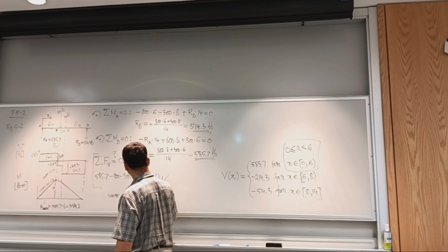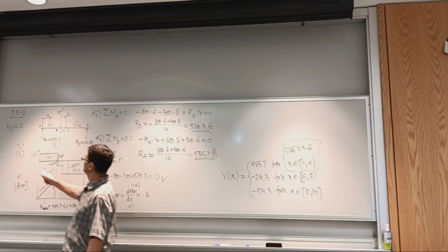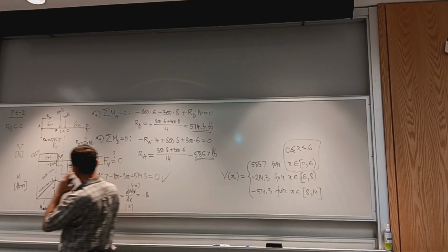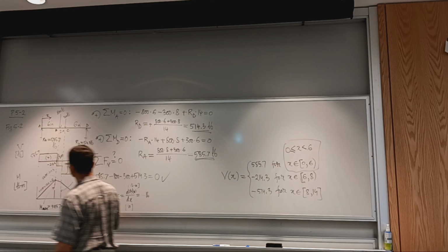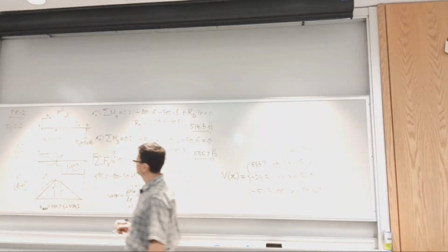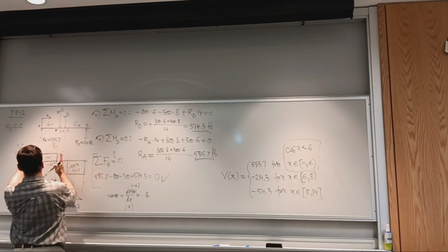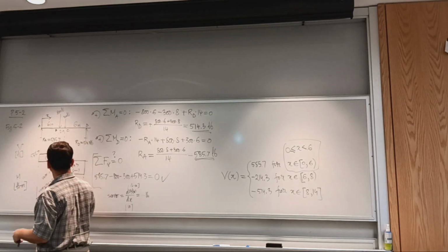So the slope is going to be in whatever value in pounds, which is the units for shear. Okay? All right, now what will be this moment here? I may be interested in the moment here, or elsewhere. So what is this moment equal to? Well, it's going to be what I have so far, the area under the curve between 2 points, minus 214 times 2.